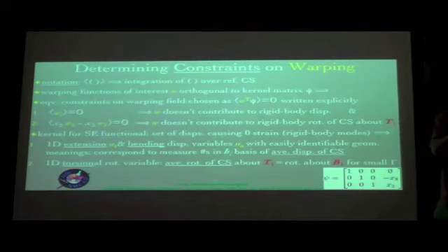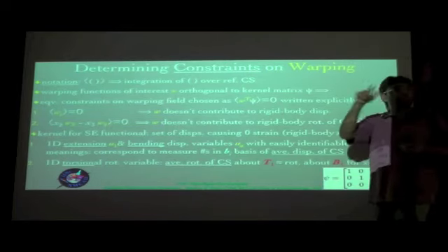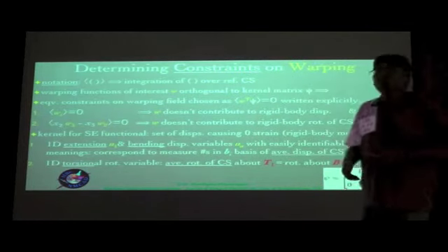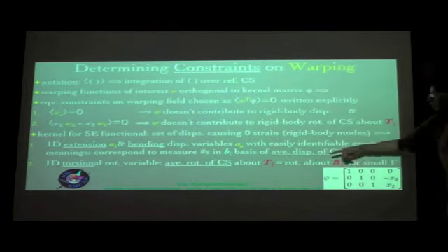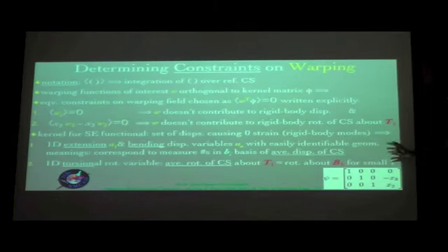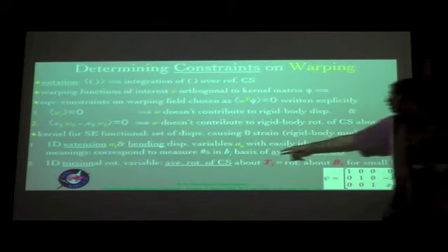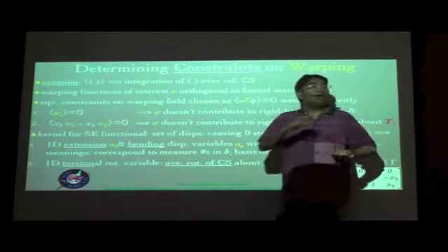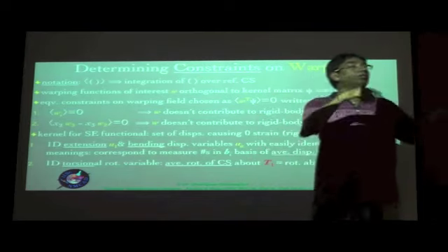There will be a difference, but the difference will be very minor because we are using small strains. Remember that the angle between these quantities is of the order of magnitude of 2 gamma 12 and 2 gamma 13, which in turn are of the order of epsilon hat times A by L, or in other words typically 10 power minus 3 for most engineering problems. And therefore you see that whether you define it as about T1 or B1, it doesn't make too much of a difference. But strictly speaking, the way we have followed and the way we have introduced the constraints, it has to be the average rotation about T1, which is what your theta 1 should be, and whose prime would be the leading contribution to your kappa 1.